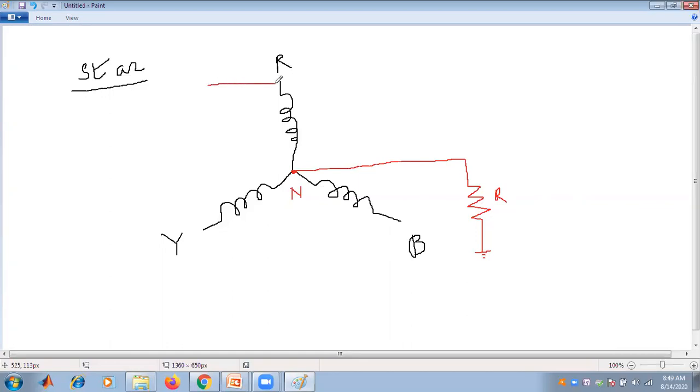this is a three-phase supply that we have obtained for the RYB. So when that particular neutral is connected with the help of a resistance through the ground or earth potential, that means any unbalance that occurs within the system will flow through the neutral to the ground. That means this is the general conception of earthing that I have told.